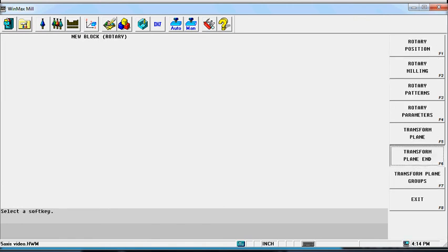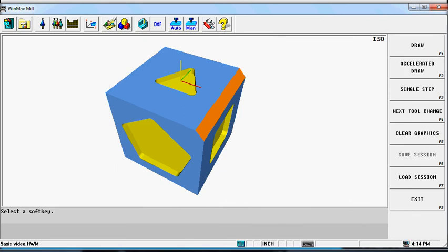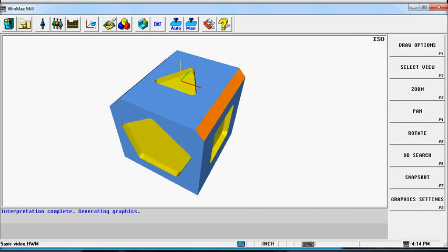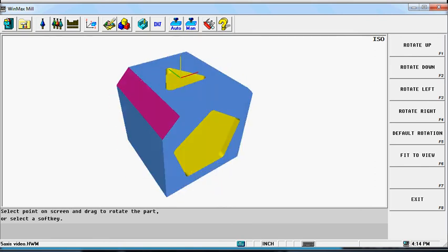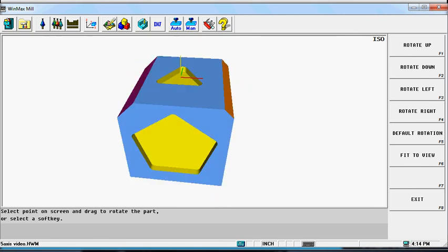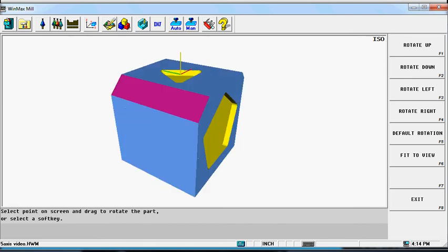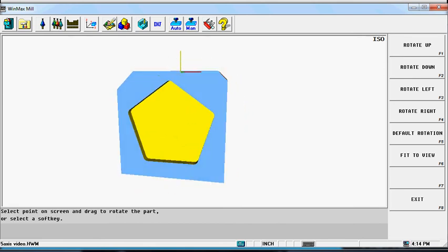And you can see that I have just cut a chamfer using the side of the tool. Now it would be very difficult to use a large chamfer tool to get one large enough to do that. So to be able to use the side of just any standard end mill is definitely a plus.